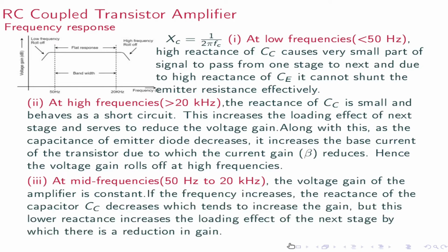It is flat. If the frequency increases, the reactance of the capacitor C_C decreases, which tends to increase the gain, but this lower reactance increases the loading effect of the next stage, by which there is a reduction in gain.